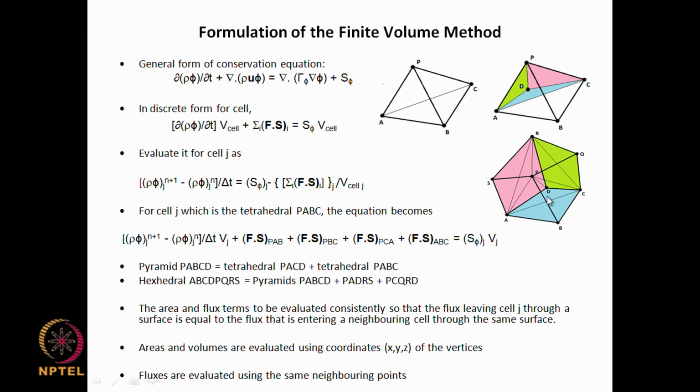What we need to do more is that we should be able to describe that general irregular shape and computational domain in terms of quadrilateral, hexahedral, pyramidal or tetrahedral elements. If we do that, over each of those elements we can then apply this formula here, and we can get an algebraic expression for the cell value in that particular cell in terms of the neighboring cell values.